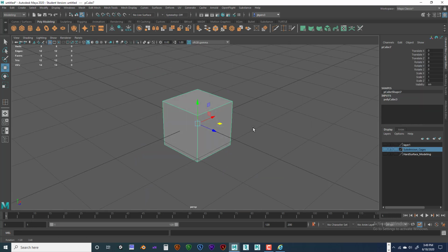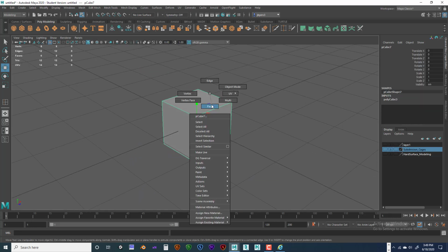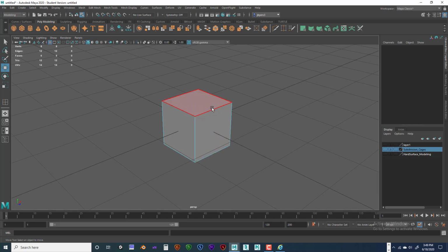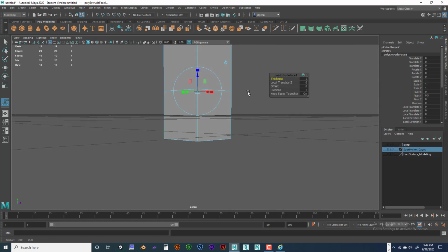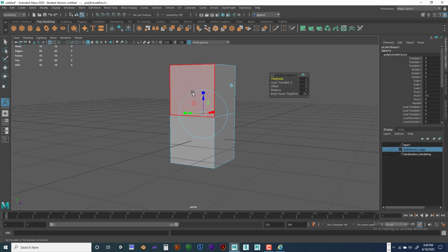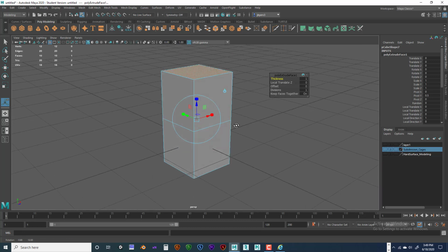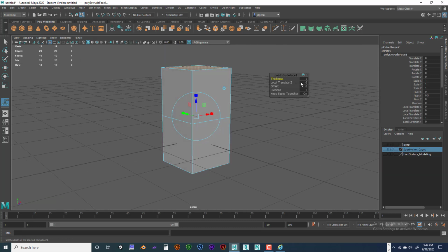Okay, the next tool is the Extrude tool, which is easy to use. You can either extrude a point or an edge. So if you do a face, you can do Control E, and that comes up with the extrude face. We've got thickness. You can do that with the distance. You can also type in the distance you want. Okay, and you can see we've got an equal amount right here, meaning the distance is the same because it's 1 unit.